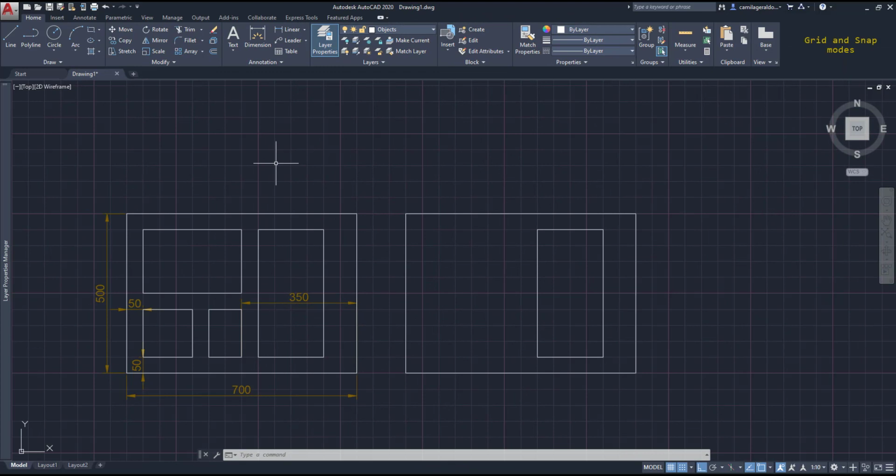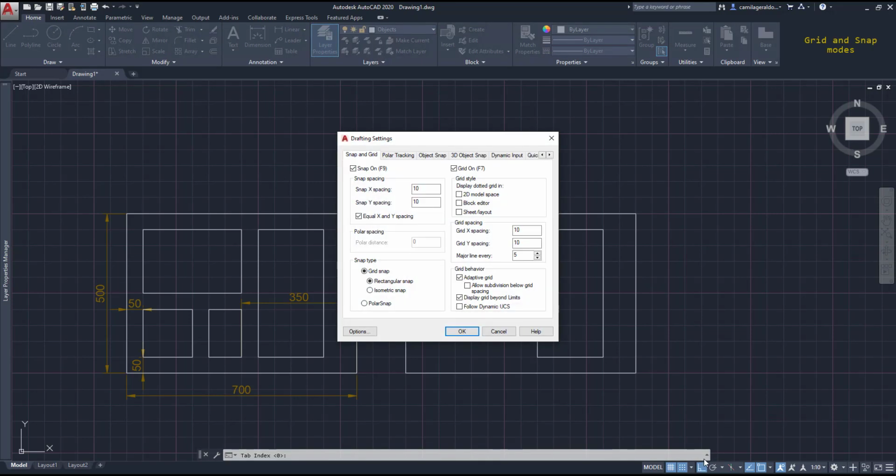Okay, now let's learn to edit the snap and grid spacing. Click on Snap Settings to modify those values. It's in the first tab of the Drawing Settings window, here. Of course, to snap only in every point of the grid, the snap spacing and grid spacing must match. Don't forget this. And the values that I have now are the settings that I used in the previous example.